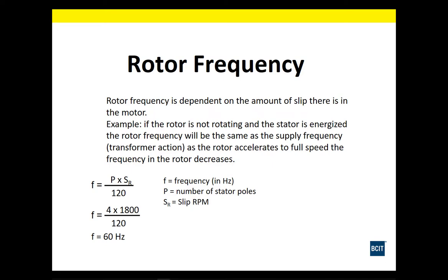Rotor frequency. Rotor frequency is dependent on the amount of slip there is in the motor. If the rotor is not rotating and the stator is energized, the rotor frequency will be the same as the supply frequency. As the rotor accelerates to full speed, the frequency of the rotor decreases.